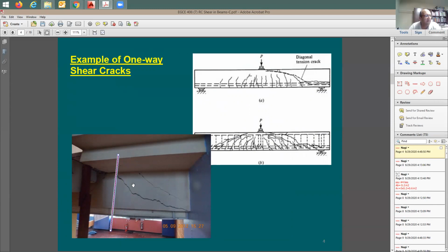It's not really 45 degrees, it's going to be less. But let's say it's going to happen about here, right? For this big crack, the distance from here to the top of the slab is going to be exactly the same as from here to there. And look at the slope of this line, almost 45 degrees, nearly.